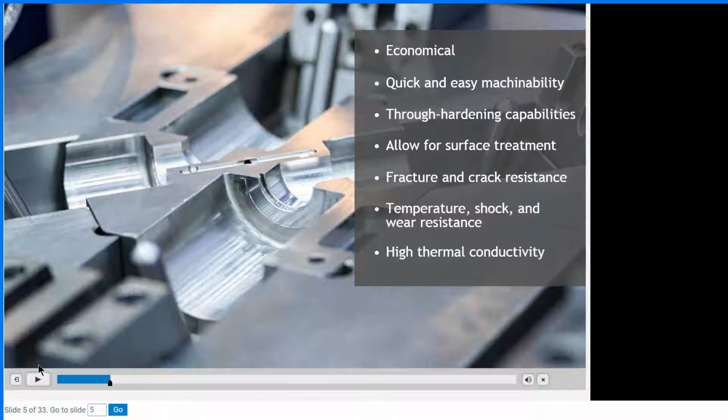But the mold makers usually have a stable of mold steels that they are used to machine and use for injection molds. But basically, this is a very important list to consider. And when it comes to cycle times, and when we talk about mold steel selection and temperature, high thermal conductivity is very important to really speed up the cooling phase. Let's take a look.